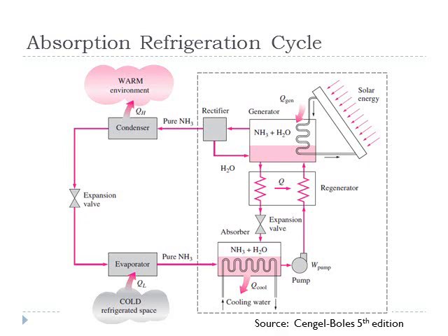In vapor compression and gas compression cycles, we had used a compressor for the compression task, but instead of a compressor, in absorption refrigeration cycle, we use a complex setup as shown in the dotted box, where we have different components which are doing some task in order to get the same effect as we had got with the help of a compressor in the previous 2 cycles.